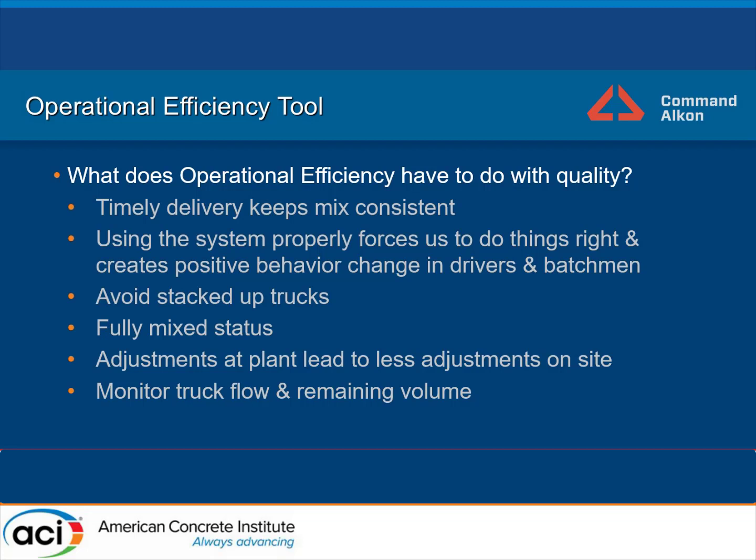Avoiding stacked up trucks, integrated with the GPS system. If we see a series of trucks stacked up and we had a high profile project where we had a low water cement ratio and they're getting stacked up before the pump and we're using super, that super could wear off by the truck that's stacked up, causing, and what's going to happen? What's the contractor going to do? Anyone? Anyone? Add water, exactly.